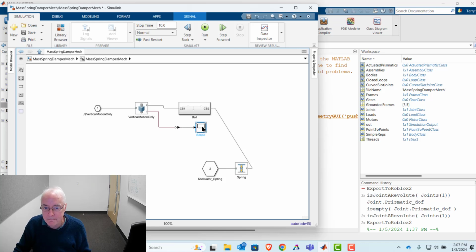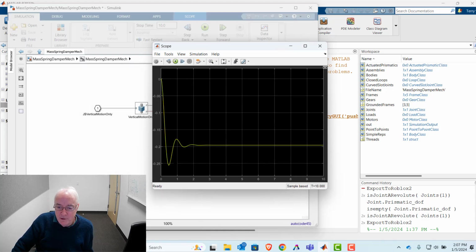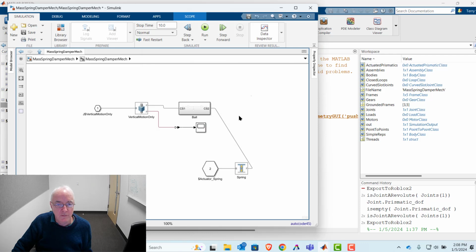And we'll hit run. Usually with those PS-Simulink blocks, I like to talk about units. I won't do that in this video just because we're going to be working in metric, and so all the defaults on those blocks will create SI units, like position in meters and mass in kilograms and so forth, right? I can see that that's exactly what we got in our previous video as well as what we got when we ran inside SimWise, and I can assure you that it is.